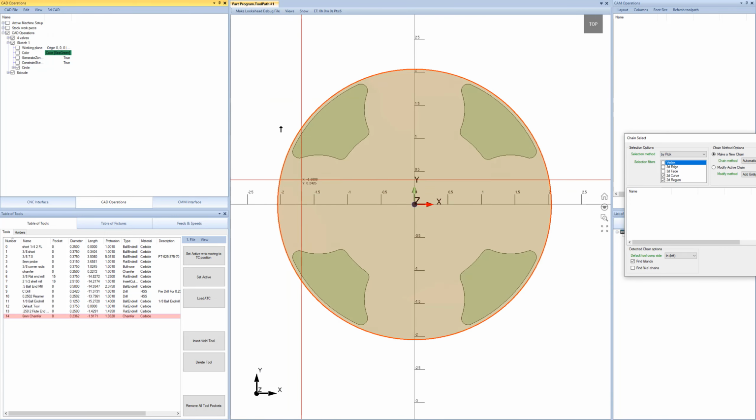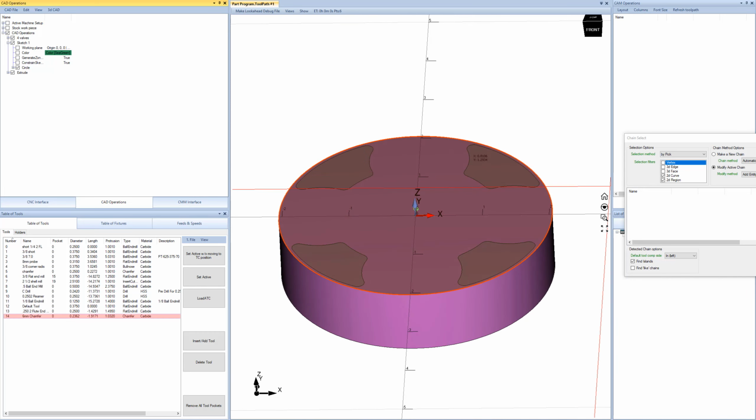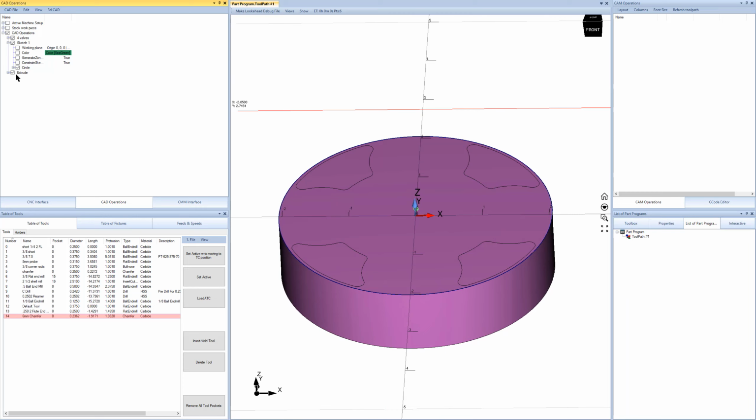And now this is kind of interesting because it gives us the extrudable areas. You can see they're highlighted in green. So we no longer have to select edges. We can select edges still. We can also select the region internally. So I'll just click on the region internally there. And I think the default extrude amount is -1. Yep, that looks good. And we'll hit E again for another extrude.